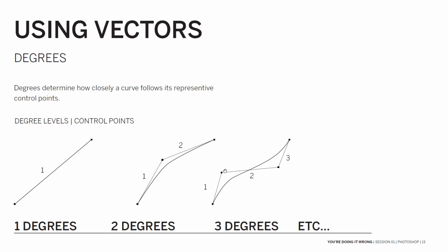If I grab this first control point and pull it up, the line will also follow a more exaggerated curve. These control points allow you to control the actual curve that you get. And you can have up to, I think, 8 degrees or more in terms of the manipulation of a line, which is pretty cool. You'll see that manipulation as we get into Rhino.